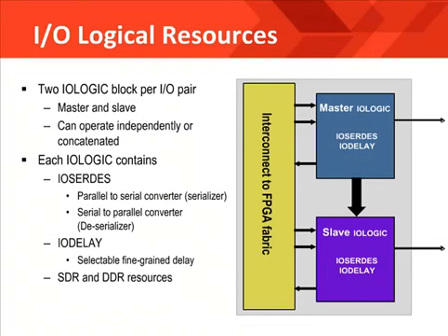Besides the register and select IO resources, there are also SerDes functionality built into each IOB. This includes both parallel to serial and serial to parallel conversion. This is a programmable functionality that can decode a wide range of signals. The O-SerDes I-SerDes combination is probably one of the most useful and radical developments.